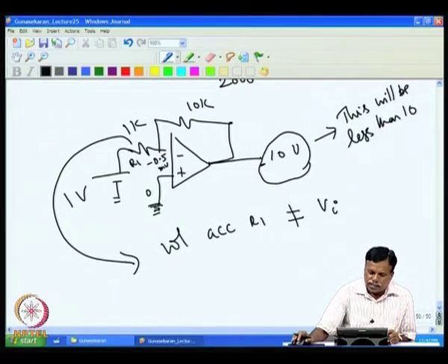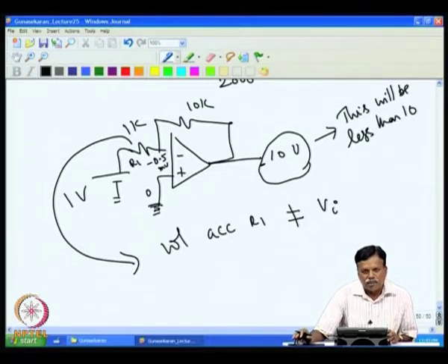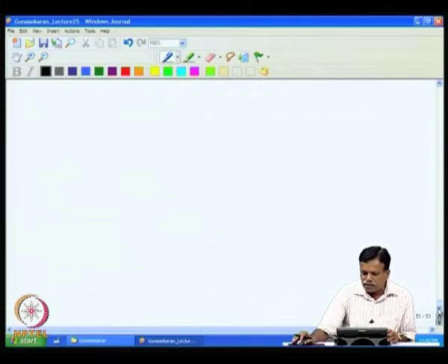So, how much error does it create, and is it possible to write a general equation to find out the error equation? Then we also have to see how to apply this error equation in our design, because this factor has been forgotten by most of the designers today, and in the actual practical world this has great implications while doing the error budgeting. So, one has to be aware of this error, and how to apply it also has to be known. So, the net result is that the set gain and the actual gain are different.